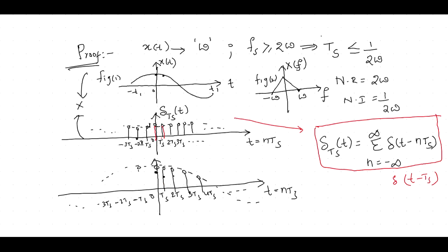We are extracting samples which are located on whatever envelope is there, same structure we will get. But in between 0 to Ts, there is no amplitude. Zeros are there. Zeros are multiplied with this. This part will be eliminated. Next at t equal to Ts, 1 is multiplied with this amplitude. That corresponding amplitude will exist here. So we are multiplying corresponding amplitudes which are located at regular intervals of time, Ts, 2Ts, 3Ts. So this is the final spectrum. What we are going to get here also amplitudes.